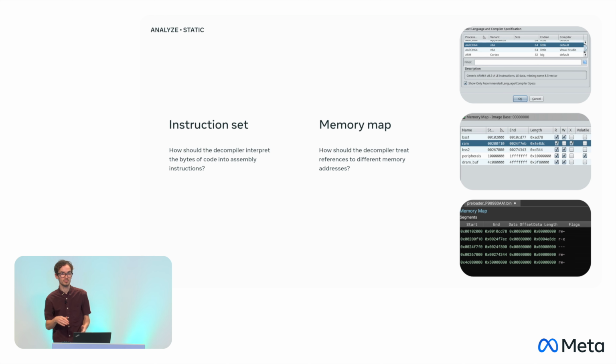So you might have a big chunk of code, but you need to know what RAM that gets loaded in, and specifically what address that RAM starts at, because most of this code isn't position independent. It's going to reference other things, other pieces of code, static variables and constants that need to be placed correctly when you go and reverse it, or else you're not going to be able to tell what's happening.